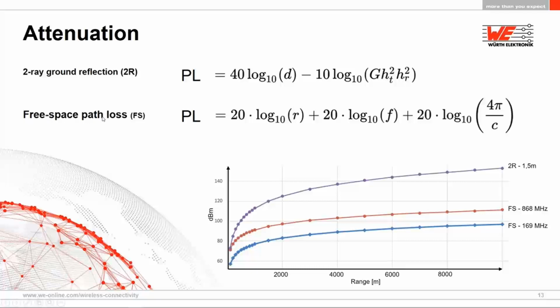And the free space path loss, the Friis model, is actually reliant on this 4 pi, you see it again, and the R, which works very well in free space, up to the moon or somewhere. But here on Earth, generally the first is a more relevant formula. I put these two together and played around a little bit here.